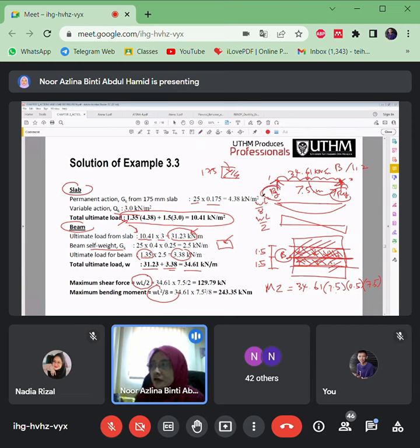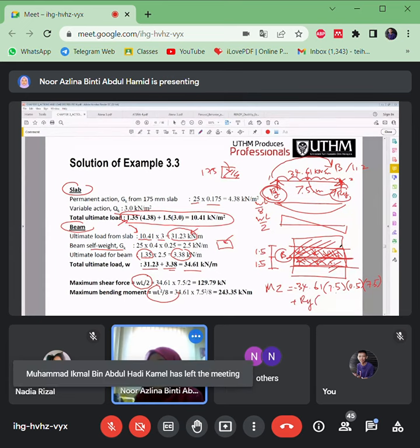And then you have another force here, Ry. So Ry will be brought to this point here for the moments, either positive or negative. Let's say anti-clockwise is negative, plus Ry, its length to this point is 7.5, and that is equal to 0.